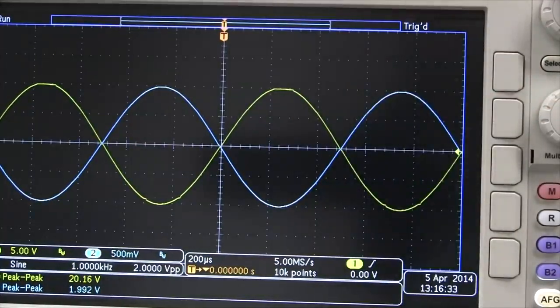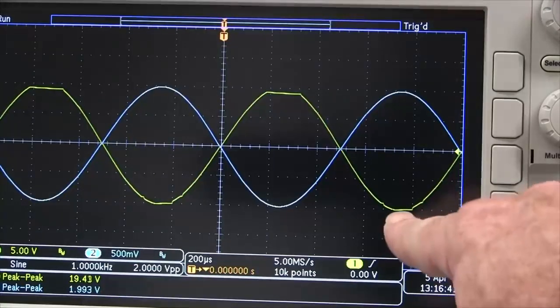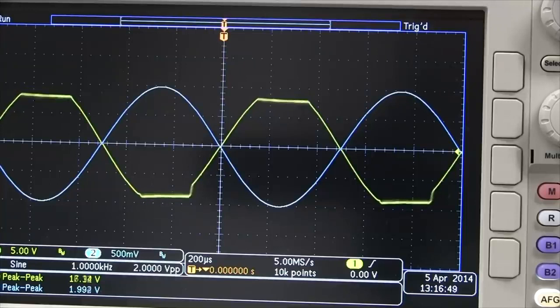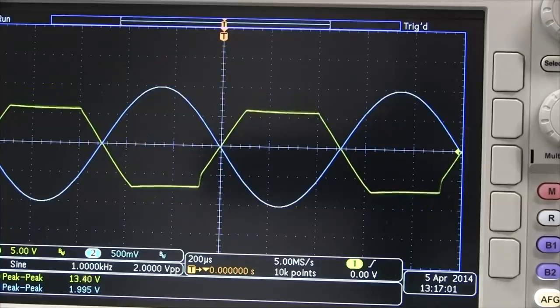Now I'll wind it down even more, because this is not a symmetrical supply op amp. It actually goes down to 0. We don't start seeing clipping on the bottom rail until a significant time after that. Now we're getting both, but if I wind it back up, that's about 11.1 volts, where we're seeing clipping on the top, and we won't see it on the bottom for some time after. So there you go. Just be aware of that.